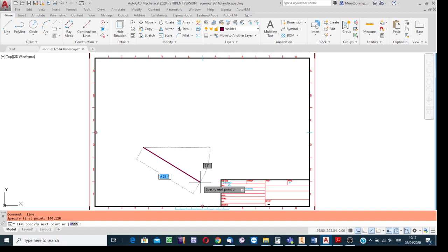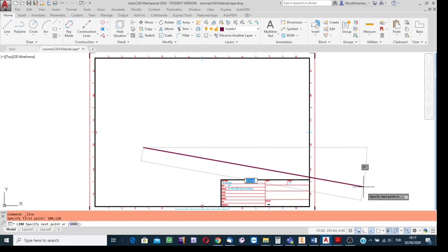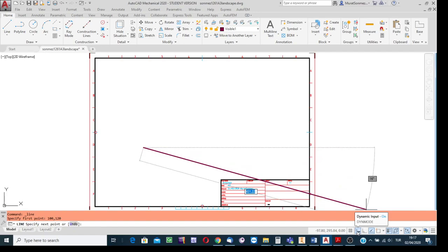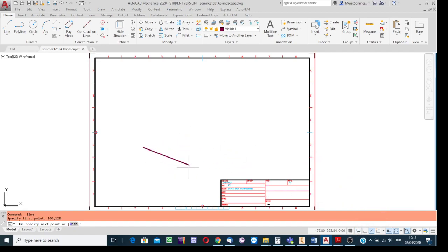Since AutoCAD, if there is no arc simulation, always measures angles relative to the horizontal reference line in the counterclockwise direction using positive angle values, it is important. Toggling the dynamic input button, for instance making it off, and then say that at this stage you need to write the inclination angle. You know the difficulty. If dynamic input is off, then you cannot find the boxes to write the inclination angle.